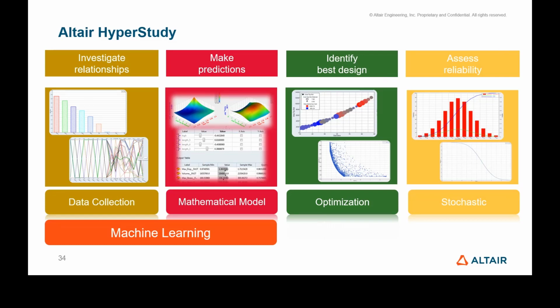And then, of course, you can also do stochastic analysis for tolerances and those kinds of things. So people ask, what is the difference between this and normally optimizing using, let's say, your own genetic algorithm? The difference is that if you were to do a normal traditional optimization, let's say a genetic algorithm takes 1,000 iterations to converge, and for each iteration, running Feko or any other tool takes you 5 minutes. That means 1,000 iterations means you're spending 5,000 minutes optimizing your structure.